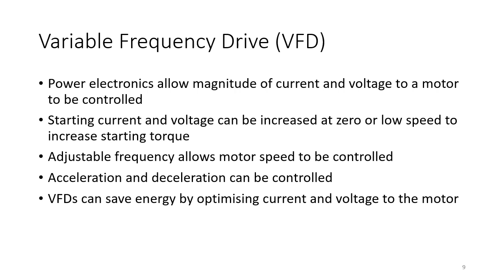Now, soft starts and variable frequency drives, they're actually the same technology. The difference is a soft start has a fixed speed, where a variable frequency drive has a variable speed. But inside, they're pretty much identical in terms of the way they're arranged. Just the variable frequency drive has a few more components for the variability part of it. So variable frequency drive, or VFD, is also known as a variable speed drive. They're known as inverters. Sometimes they're just known as drives. What a VFD is, it's a combination of power electronics, and that allows the magnitude of current and voltage to the motor to be controlled.